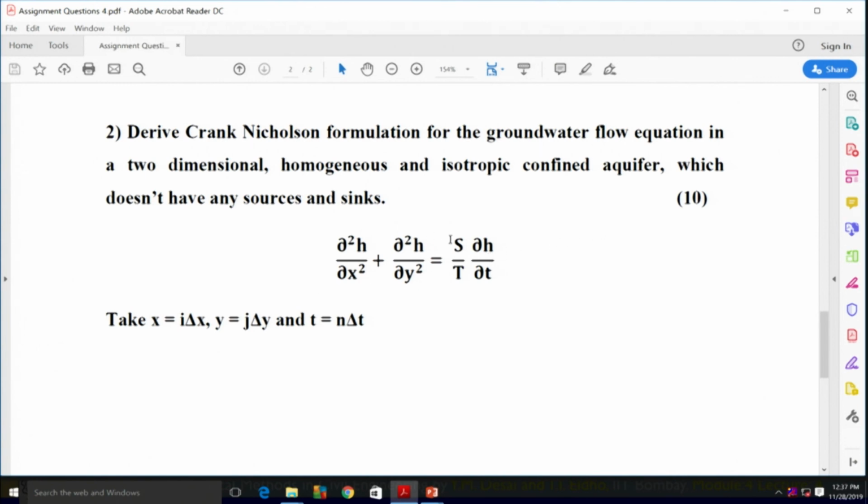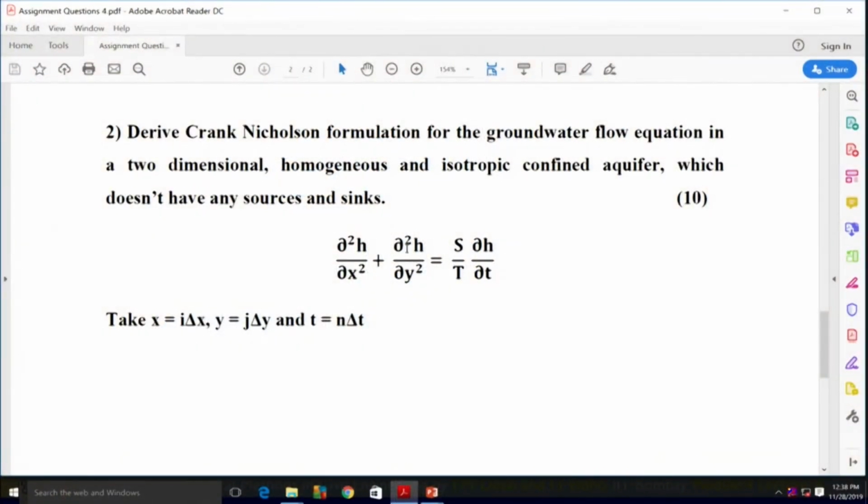Here we have already seen in lecture number 4, module number 4 the one-dimensional parabolic equation or heat conduction problem, del square u by del x square is equal to del u by del t. In a very similar way, now you are asked to extend it to 2 dimensions. That is very straightforward. You can do it as an implicit formulation. So, this is the governing equation, and this is also given as an assignment.